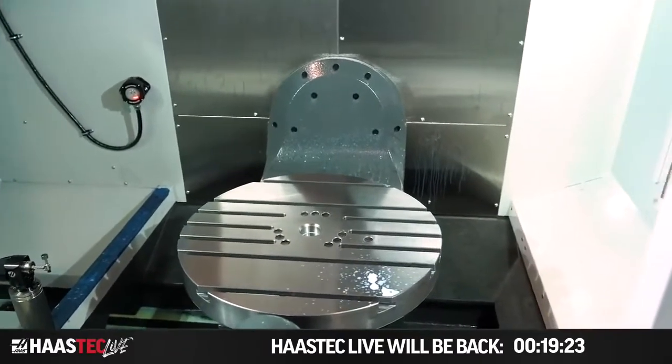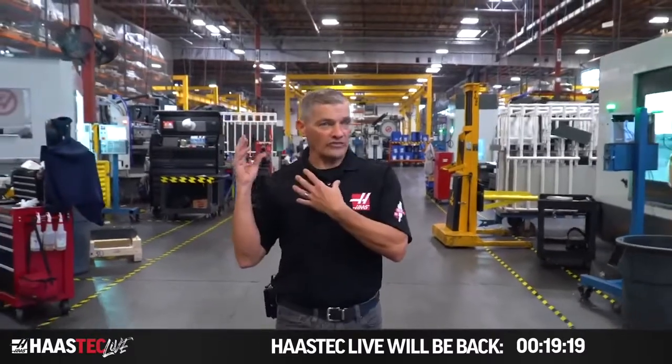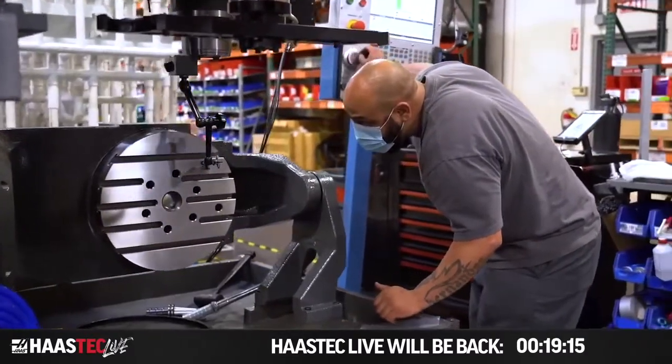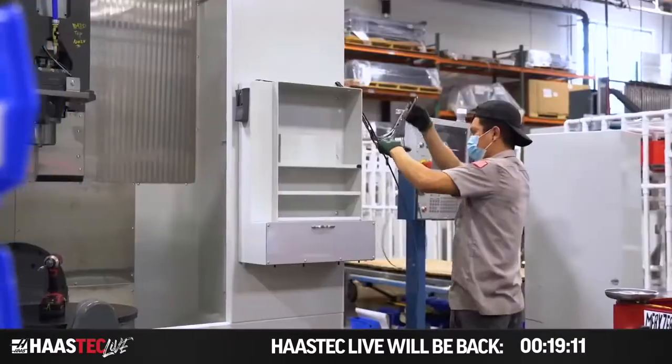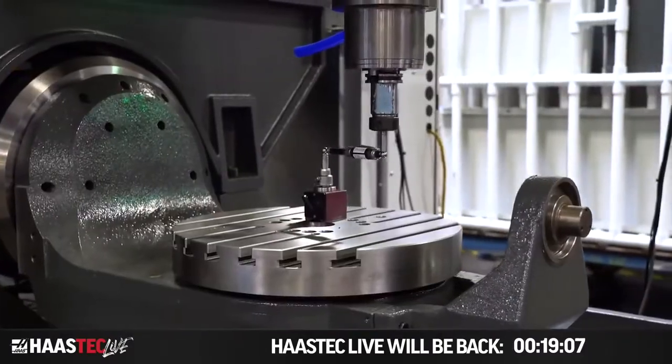So of course, when we come to the final line, the idea here is after the casting assembly is done, here in the final line, we take care of the geometry of the machine, aligning all the axes. Then we put on the sheet metal, install the control, and then do all of the testing that goes into making sure that the machine is ready to go.